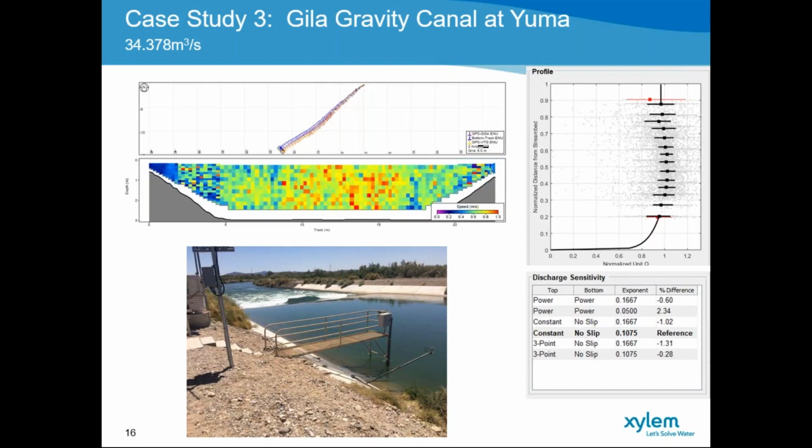There are two factors impacting this specific site, which is very common with a lot of irrigation sites. There's an actual control upstream created by the cofferdam that wasn't removed, so there's an acceleration of the flow there, as well as during peak releases this gauging weir is submerged almost 100%.